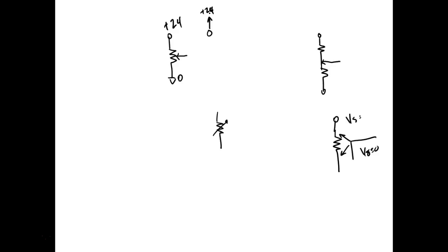Well, technically, a potentiometer is a variable voltage divider. That's what it is. So what I'm doing is I'm setting these two resistors right here. If it's a 10K pot, if this was 3K, then down here, this would have to be 7K. Because when they say it's a 10K pot, that's the resistance that you're dividing up. And then I could calculate this, right? You understand? This guy right here would drop 7/10 of the voltage. This guy right here would drop 3/10 of the voltage. It's a 10K pot.